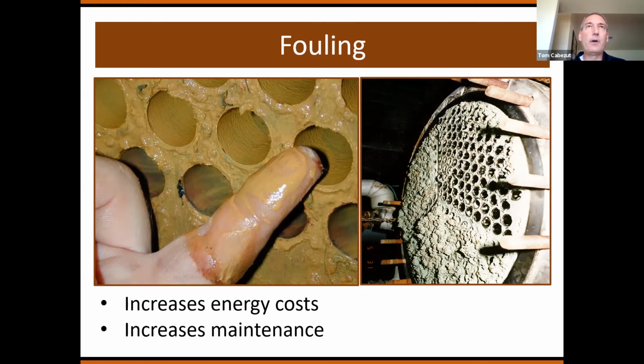So for example, if you are running a system at 2,500 hours a year and you're paying 13 cents a kilowatt hour to run a chiller, let's say it's 500 to 1,000 tons. That cost can be anywhere between $75,000 to $150,000 a year. By maintaining that